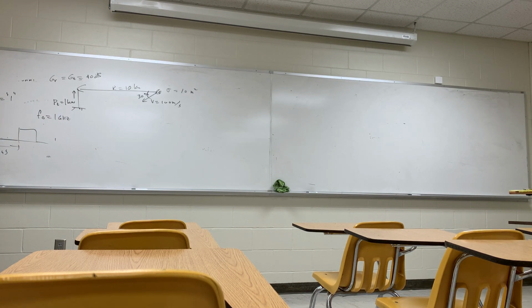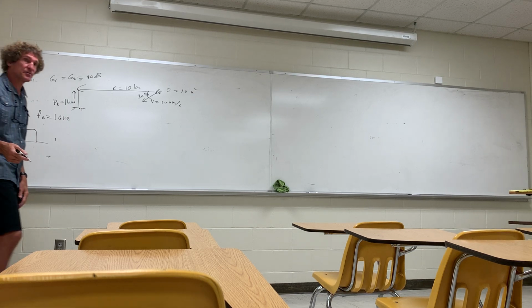Y'all follow me what I'm trying to do here? I've got a transmitter frequency of 1 gigahertz, so these things would have a 1 gigahertz oscillation rate inside of 1 microsecond, which means if it's 1 microsecond and that's 1 gigahertz, there would be 1,000 cycles in one of these things. Then it would be dead, then 1,000 cycles. So here's some of the things that have been asked for.